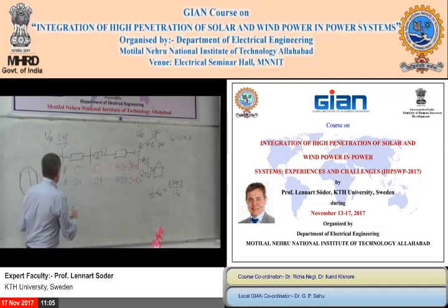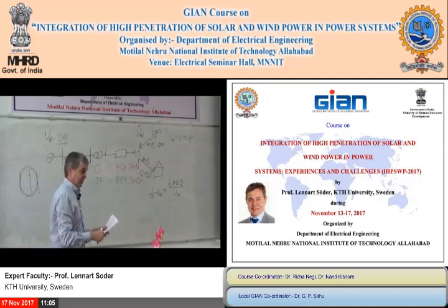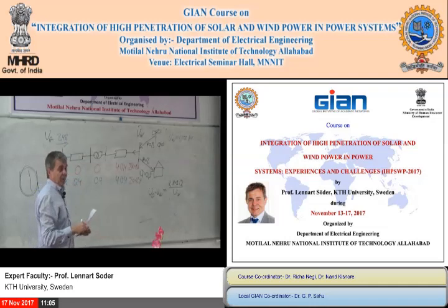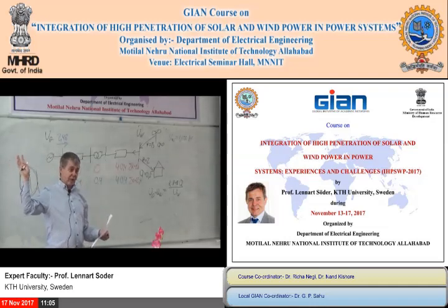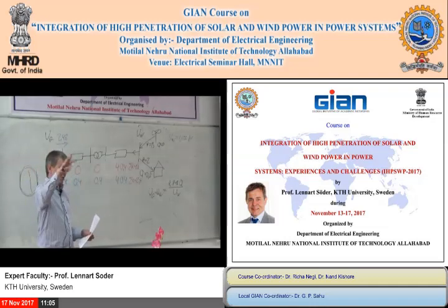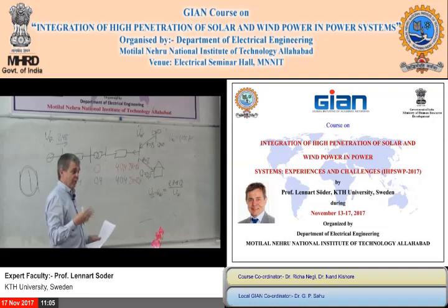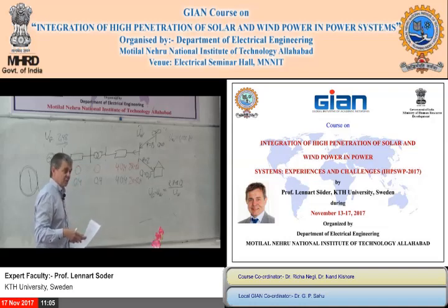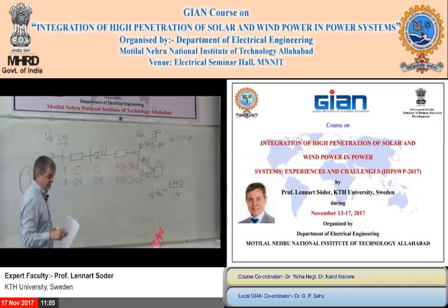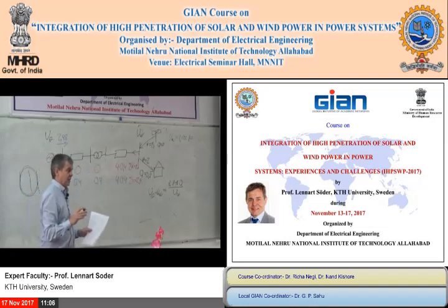And in cable, in reality, you have the conductors much closer. So that's why the reactance goes down when you have cable. And that is very important, because here you have a huge amount of overhead lines. We had it earlier in Sweden also, by cablifying more and more. What is happening when you cablify is that you reduce the reactance in the system, and you get more capacitance, because the lines are closer, so you get higher capacitance.